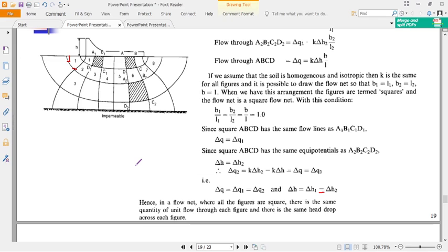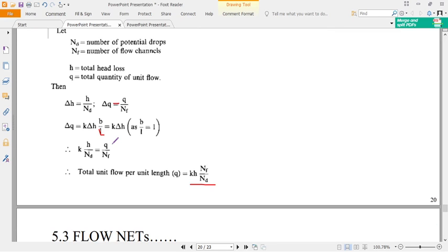Now using this equation, equating it to this times K, we can make q the subject. Equating these two, we can make q the subject. Is that okay? Now q is equal to K times H, where H is the head, this head here, and K is the permeability of the material. That's why it's important to determine K, the permeability between the impermeable layer and where the dam is constructed. If the dam is not constructed on a permeable layer, this material may be clay. It may be clay. Is that okay?